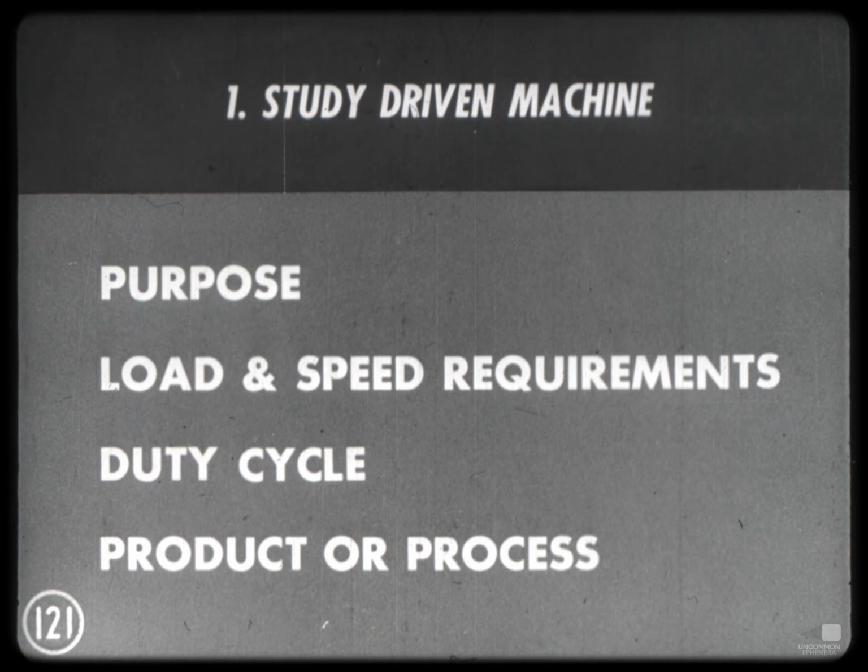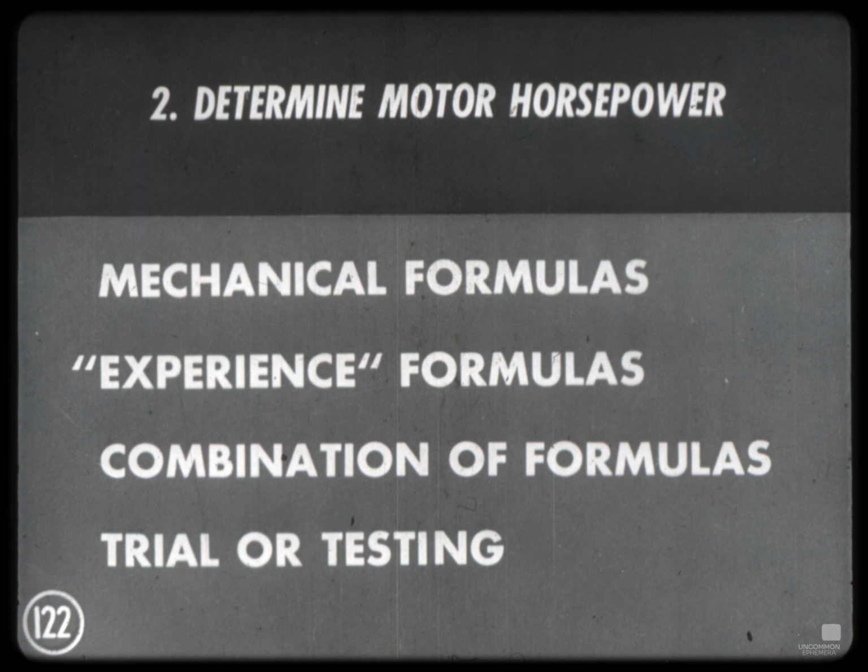1. Study the driven machine. Determine its purpose, its load and speed requirements, its duty cycle, and the product or process involved. 2. Determine the motor horsepower. This usually is done through mechanical formulas, experience formulas, a combination of the two, or through trial or testing.